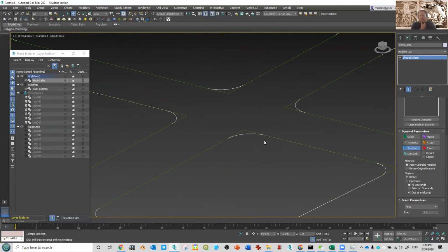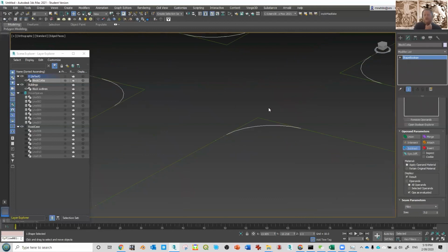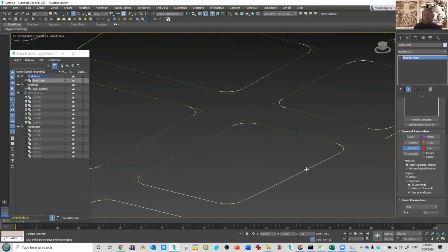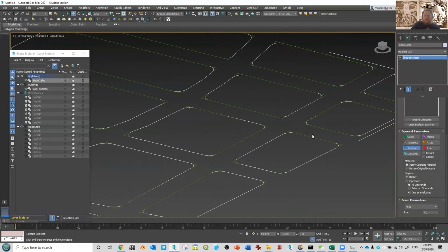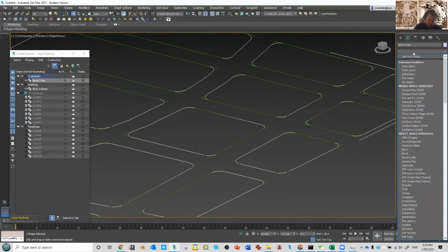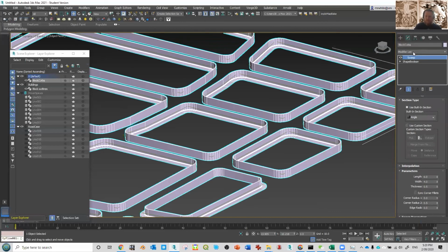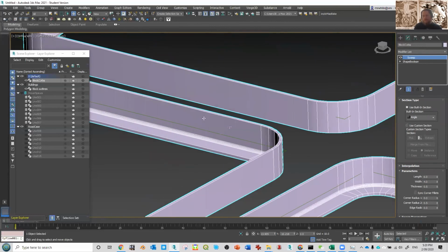And there would be a couple of ways you could do this. You could do another spline offset on it, and you could keep your original spline, and then you could extrude it to a footpath height. So 150 or something. That would be one way to build the footpath. You could do a loft, which is probably more complicated than it needs to be for this particular scenario, or let's try something I don't think we've done in this class, which I think is called sweep. Sweep, super useful, pretty simple.